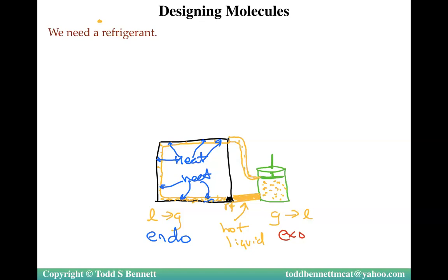And as it goes in, it eventually will get compressed, which means I'm going to have heat escaping. I'm going to do that in red, sorry. I want to have heat escaping the chamber. So ultimately, I'm going to take heat from inside here, put it in the walls of this gas. The refrigerant is going to be piped back out into the compressor. The compressor is going to compress, releases heat here, releases heat here. So you release heat outside of the system, and you absorb heat within the system.